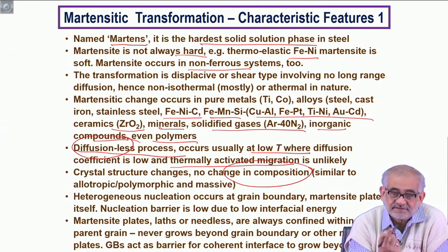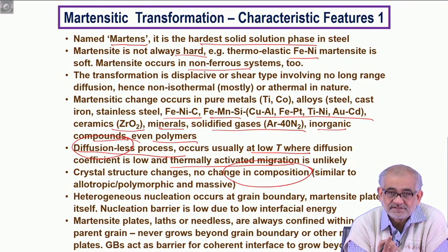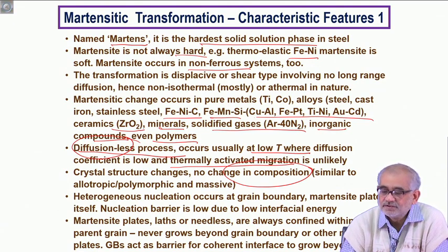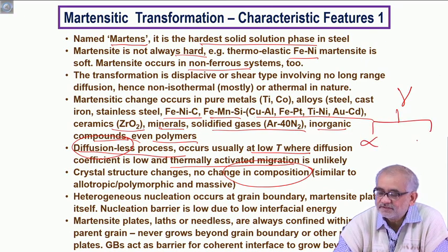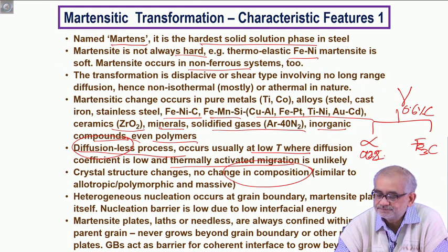So, let us say you are dealing with a 0.4 or 0.6% carbon steel, which is what austenite will contain. From 0.6% carbon, you swing all the way to two different phases, alpha and Fe3C. So, you are now talking about a phase compositional variation as large as this.